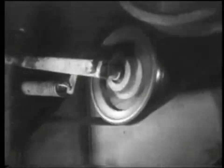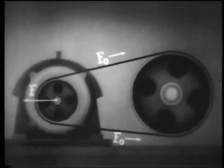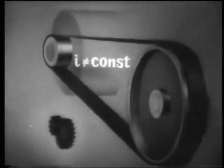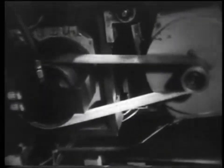The belt transmission consists of two or more pulleys, on which a belt is tensioned, transmitting the circumferential force by friction. Compared with gears, the belt drive has large dimensions and slightly less efficiency. They do not provide synchronicity of shaft rotation, but despite these limitations, the scope of their application is very large.